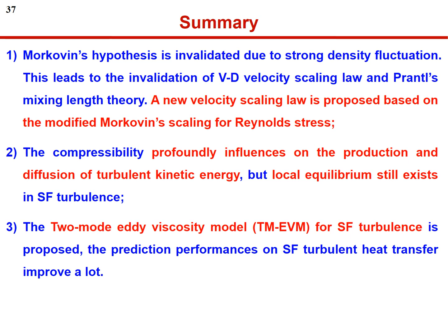Second, compressibility profoundly influences the production and the diffusion of turbulent kinetic energy, but a local equilibrium still exists in supercritical fluid turbulence. Third, the two-mode eddy-viscosity turbulence model for supercritical fluid turbulence is proposed with good prediction.